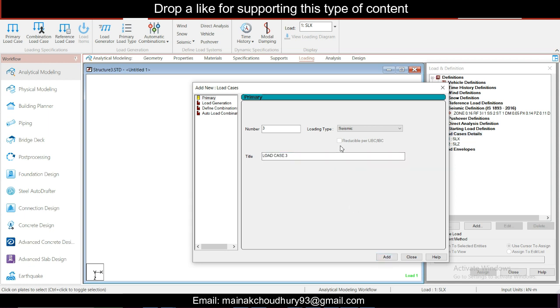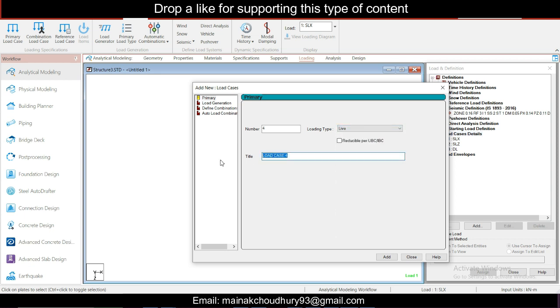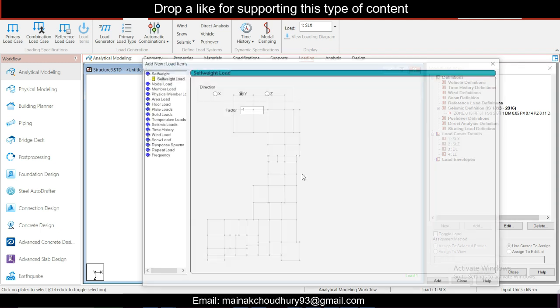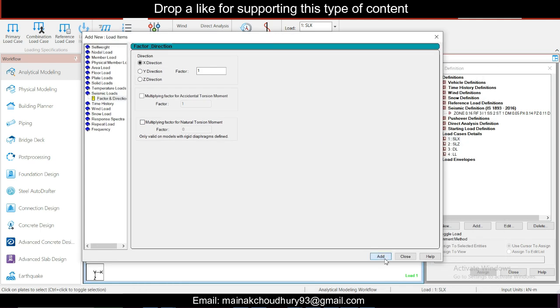Okay, seismic load in Z direction, and then we have the dead load, then we have the live load. And then if you want to check, you can add the modal analysis as well, to simply check whether the structure is stable or not. We cannot design by modal analysis for now, but we can check whether the structure is stable or not using it. So just add seismic.